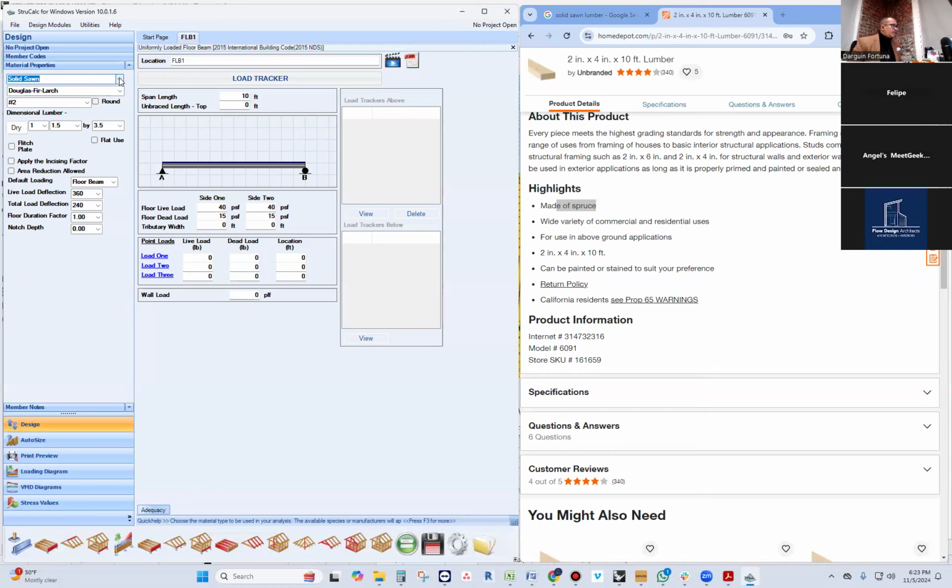So for good practices, for really good practices, you're going to use solid sawn for general floor framing, traditional conventional framing, nothing too elaborate. Spans are not too long. So for floor framing, you're going to be using solid sawn generally, likely 2x8s, 2x10s, 2x12s.